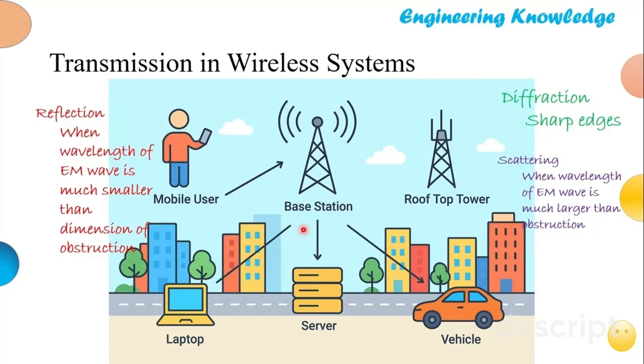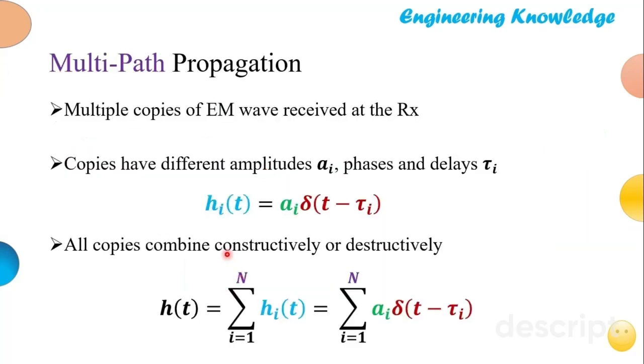Wireless transmission, I have discussed many times, consists of reflection, diffraction, scattering. So everything is very complex here, and the signal that reaches wirelessly suffers a lot of attenuation and phase shifting, and therefore the channel model is given by an attenuating factor and a delay, a group delay. So this I have discussed in detail in my first few videos. You can latch on to those videos.